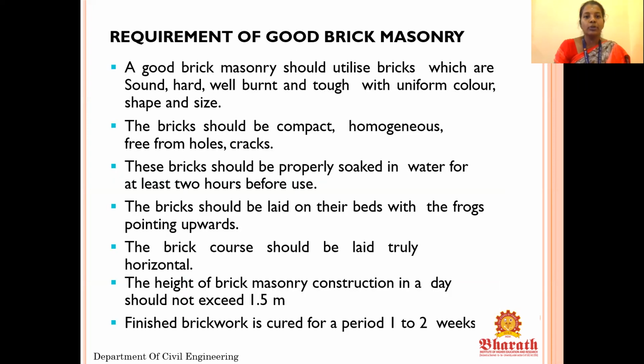Next we are moving into the requirements that we have to follow for good brick masonry. A good brick masonry should utilize bricks which are sound, hard, well burnt, and tough, with uniform color, shape, and size. So we have to check that the brick sounds right. If you tap it with a certain instrument, the brick sound should be clear. So you can hear that sound.